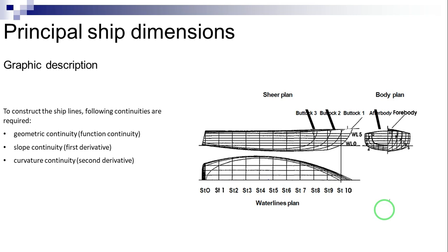The curves of plans shown above are best represented using parametric spline curves, by which the curves are defined by a parameter S rather than directly by X and Y coordinates. The parameter S is defined as the cumulative length of segments of the line from the start point up to the point in question.